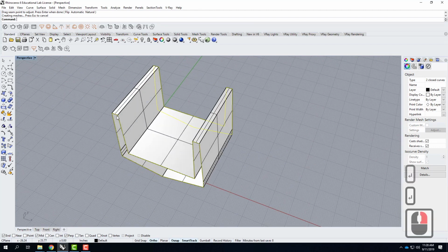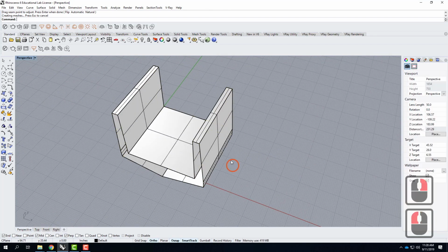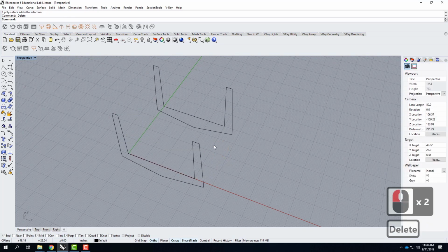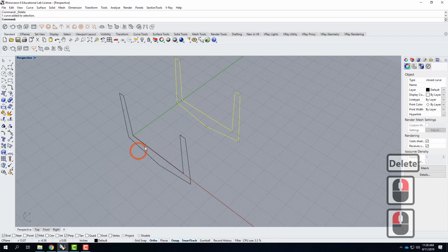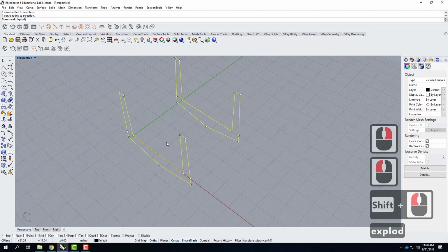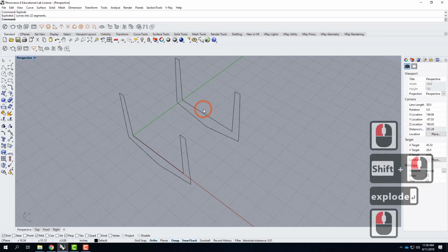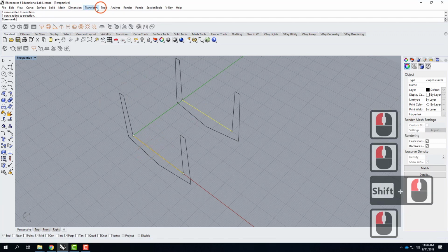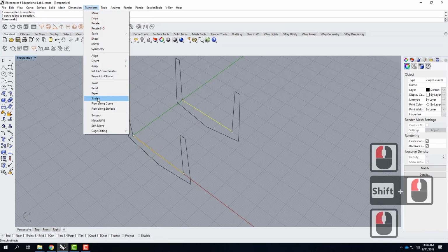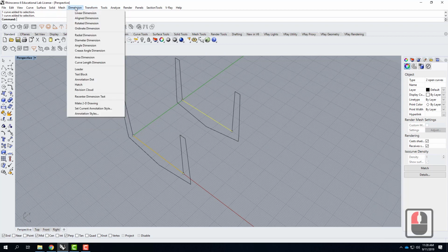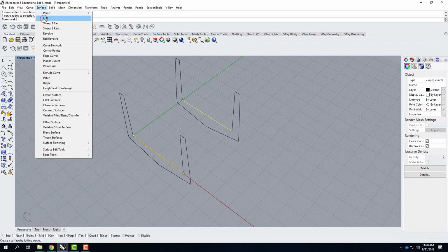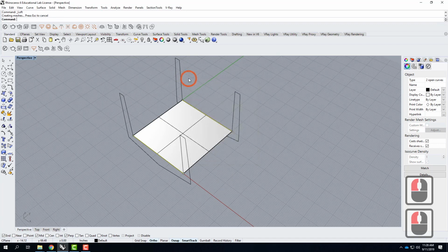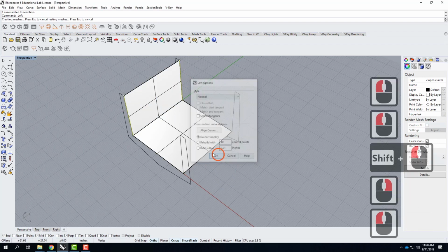Now these lines on the outside were continuous closed curves where they were all joined together. Sometimes you have curves where they're exploded. So in this scenario, I have separate curves. I could go through and manually do this to this and then loft. And then pick the next set of curves there and loft those together.